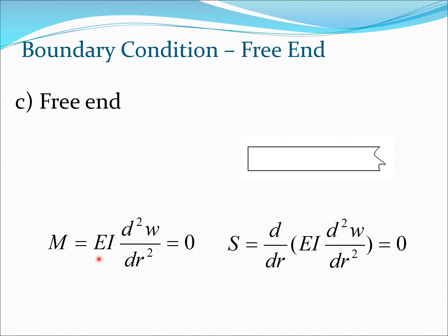which essentially would mean that if you had a uniform beam type situation, you would get the second derivative and the third derivative to be 0 at the free end, the derivatives being with respect to displacement.